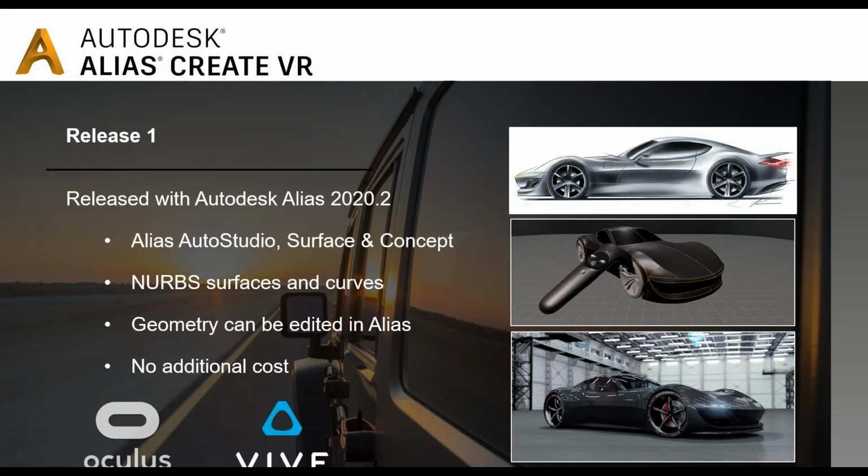So a little bit of history. We released the first version, the first release of Create VR, with Autodesk Alias 2020.2. It ships with all of the current versions of Alias, so it ships with Alias AutoStudio, Surface, and Concept. The first release was based on a NURBS surfaces and curves workflow. So you would build up your geometry on curves and then use those curves as reference or build off of those curves using NURBS surfaces.